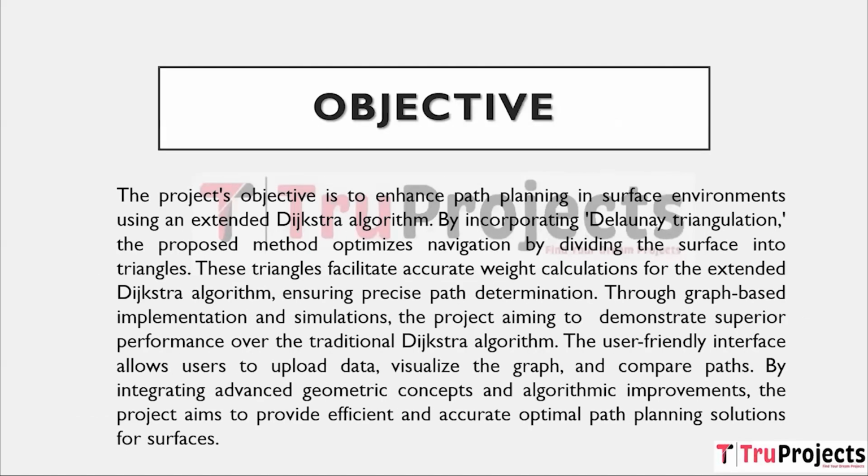Coming to the objective, the goal of the project is to enhance path planning in surface environments by utilizing an expanded Dijkstra algorithm combined with Delaunay triangulation. The proposed approach aims to improve navigation by splitting the surface into triangles. These triangles allow for extracting path finding by facilitating accurate weight calculations for the expanded Dijkstra algorithm.